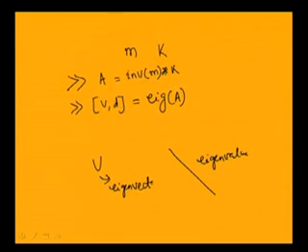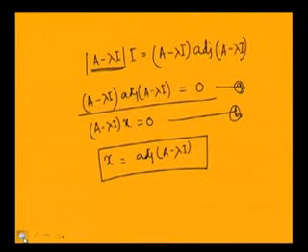So, by using MATLAB also you can find the eigenvalue and eigenvector. When you are doing it by hand or manually for a system with fewer degrees of freedom, you may use this adjoint matrix method. So, adjoint of A minus lambda I you find to get the normal modes of the system. Let us take one example.